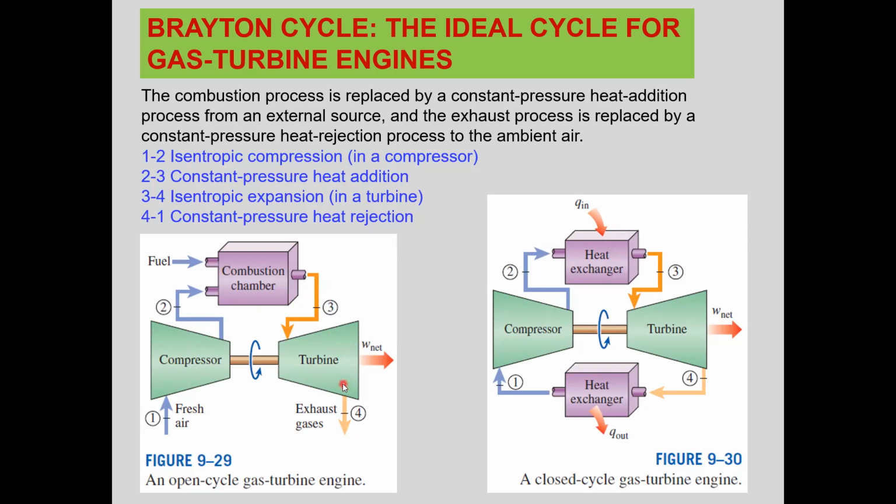They rotate the turbine blades as the combustion gases' temperature and pressure are reduced as they flow through the turbine. They leave the turbine, the exhaust gas or combustion gases, at much lower temperature and pressure, here ideally at atmospheric pressure. And of course, there is a net work output. This net work output is equal to work output from the turbine minus work consumed in the compressor.